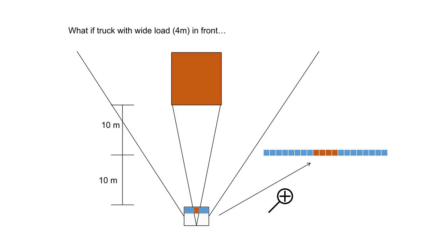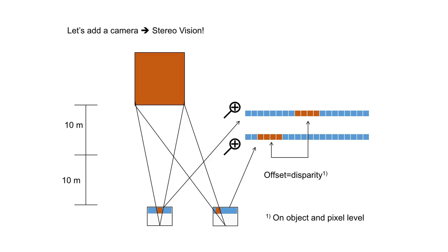We would make a major error in the distance estimation. So you need to estimate the width of the object to be able to use this particular method. Again, this was a very basic and conceptual demonstration of the size-based estimation. There are, however, methods that allow for camera distance measurements to be largely insensitive to the size of the object.